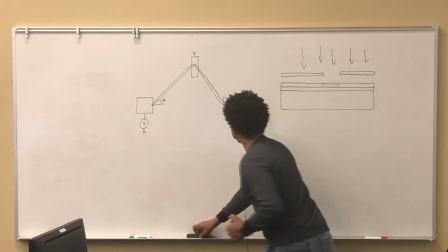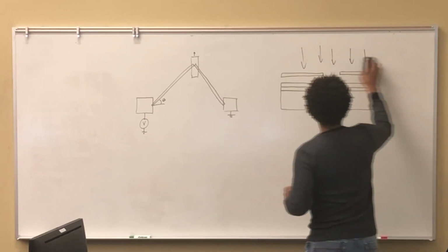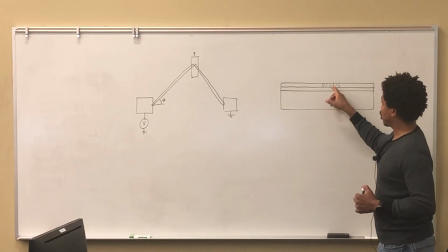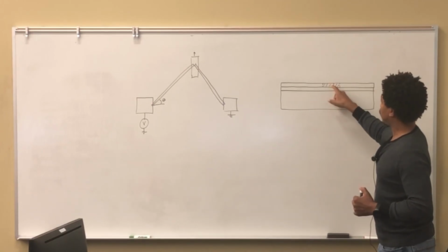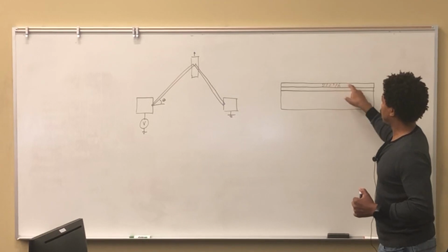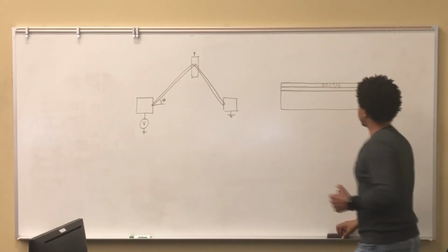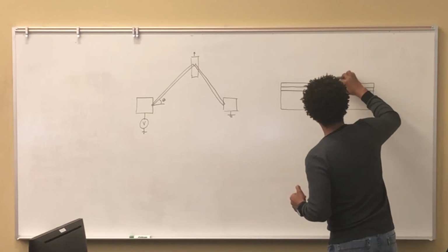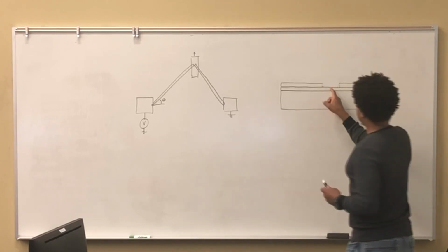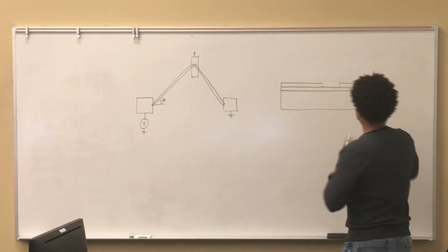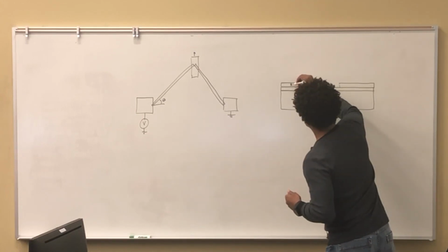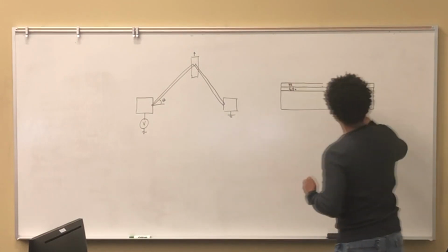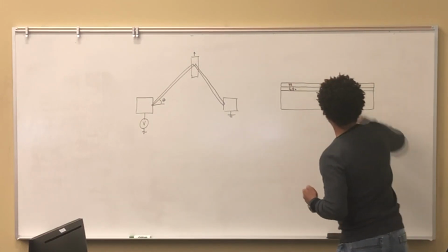And so what happens is that now you have this material, and there's certain types of etchants that will etch away photoresist where the bonds are broken and leave behind photoresist where the bonds are not broken. And so this part goes away. And so what is exposed now is this surface, this silicon dioxide layer. So I'll just put PR for photoresist and SiO2 for silicon dioxide. So the silicon dioxide is exposed.